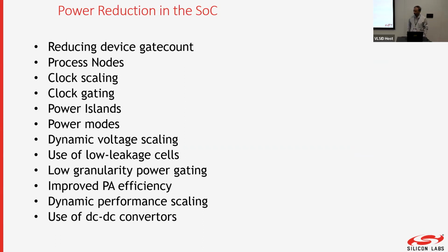You know, when CMOS came, it was magic. How can a system not draw any current and still do it? Complementary, right? So one is on, one is off. It seems like magic. You don't consume any current. It's active. It's driving something, but it's not consuming current. However, during the transition from 1 to 0 or 0 to 1, there's a small period of time in which both of them are intermediate.